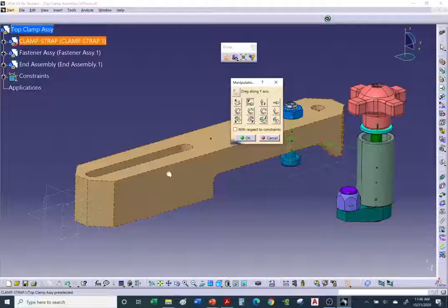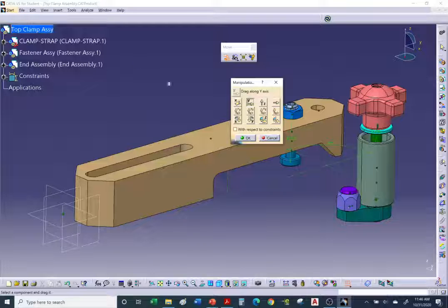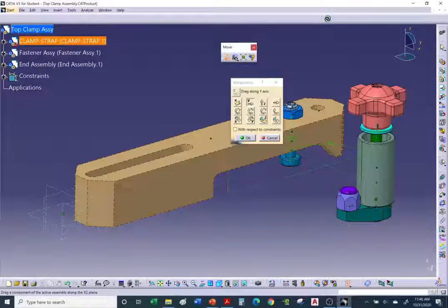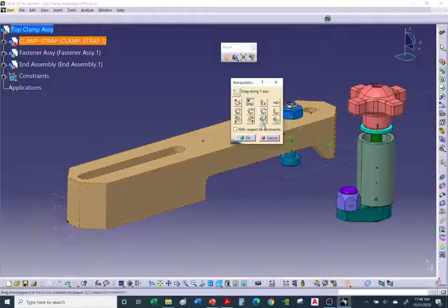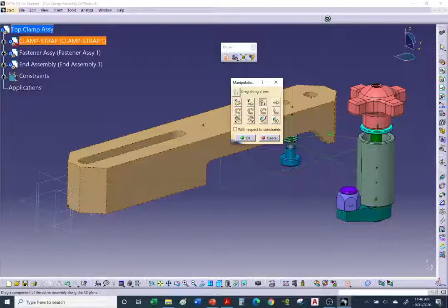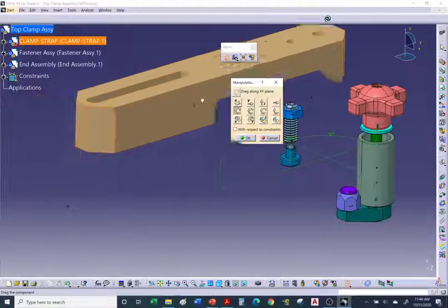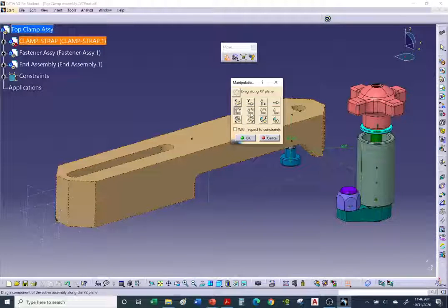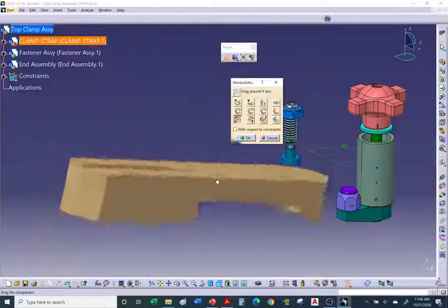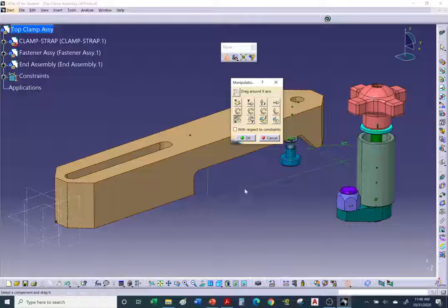Okay, now the brown strap, it's by itself. It's not inside of a binder. I can also move that if I like. In the Y direction, I can go into Z. I can also rotate. My mistake, move it about, translate it about a plane. Let's go the XY plane. So I can slide it about the XY. And I can rotate it about an axis. Notice it's rotating about the x-axis. Okay, so you can rotate.